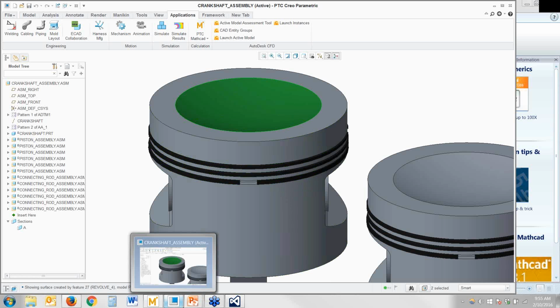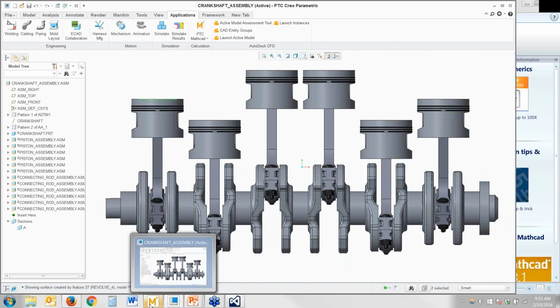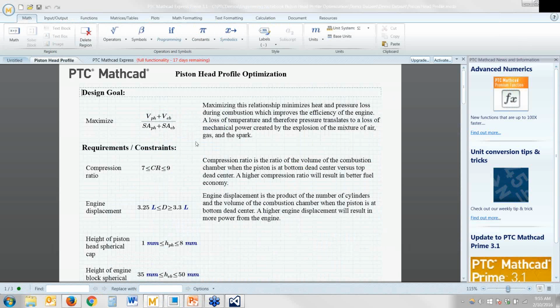And when you talk about optimizing that, really, what you're looking for is a couple of things. In that region there, you want to have the most volume and yet also the least surface area. The bigger the volume, the more air you can have in there, and in this particular case, there's more air for your fuel to burn. And heat can only escape, at least there's some heat that escapes through radiation, but aside from that, primarily